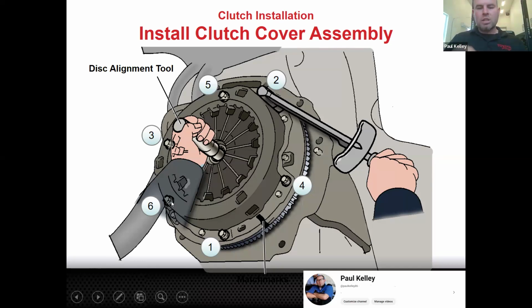There's a sequence and there's a torque spec. That's a more critical torque spec. If you under torque it, not only will it loosen up, but it's not really setting the springs well. The reason there's a sequence is because we need to draw it in nice and flat. If you pull it down on one side, the pressure plate may sit crooked on the clutch and put more pressure on one side. That'll make a hot spot on the pressure plate and the flywheel. So we draw it in nice and square and then torque it in sequence to the spec.